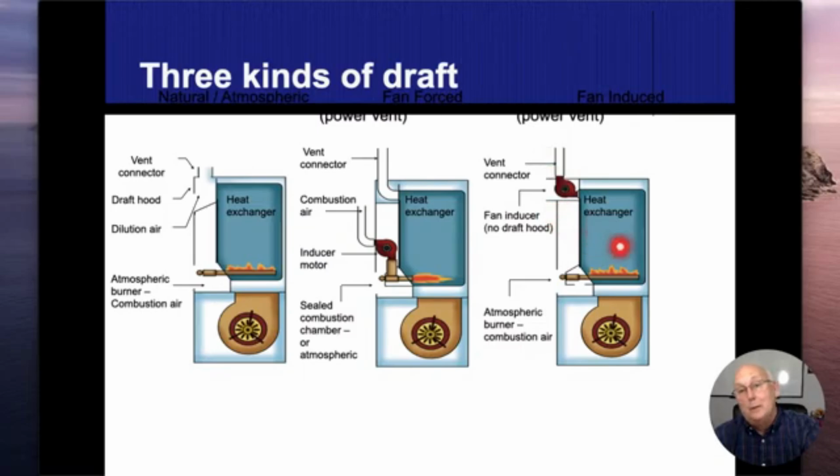So now, even though it's a smaller fan and not as powerful as our blower fan, when that burner kicks on and the inducer is going and it creates a negative pressure in there, at least if there is an opening, we're going to have that secondary safety thing where air is going to come into the heat exchanger and not into the circulation air. And then if I have a positive pressure when the blower fan's going, that even makes it a stronger pressure differential. So the less likely a chance that comes in there.